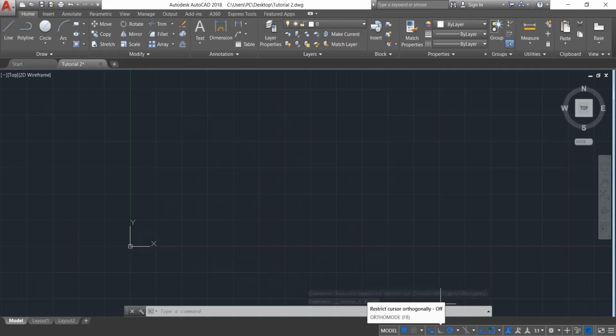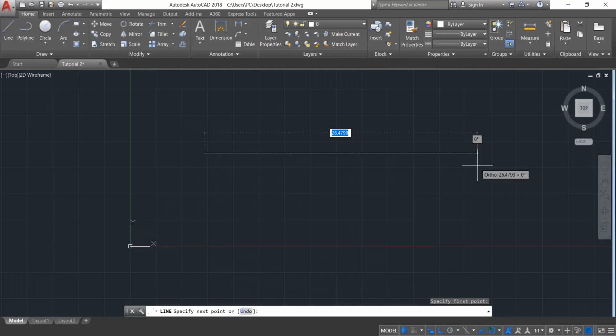It means that it is going to move either vertically or horizontally. For now, it is turned off. Let me turn it on. Now I can draw that line. But if I try to draw at a certain angle, it can't, unless it is 90. So this is the one that can draw those straight lines fast for you.